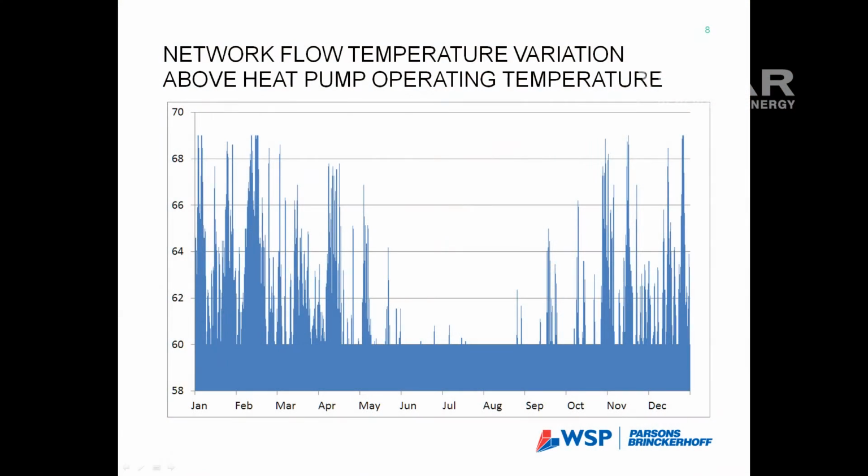However, the heat pump could only deliver 60 degrees to the customers. However, by considering that the design day conditions for heating design only occur for a few hours a year, actually the requirements are a lot less for the rest of the year. We could relax the size of the radiators a bit and use some top-up heat for the few hours a year that was necessary. That allowed us to use the heat pump to deliver most of the heat throughout the year.